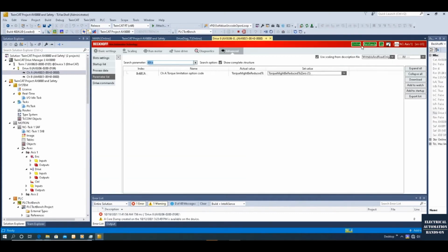And let's check this 6060, this mode of operation. Currently, we power on the motor, and by default, our motion is at the CSP, the positioning mode. Okay, so using the MC torque control, we can switch between the positioning mode and the torque control mode back and forth. So by default, the drive is using CSP mode.